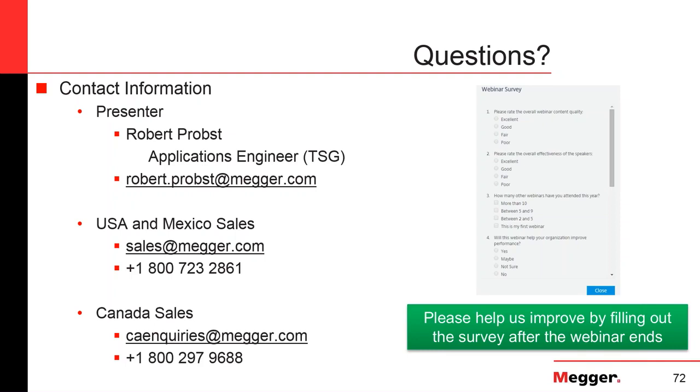If you have a source of limited power, you can either generate very high voltage and very low current, because your power is restricted. Then we're talking about insulation testing. That is a high voltage test at very low current. And the opposite is pretty much primary injection. There, you transform the voltage down and transform the current up to very high currents.